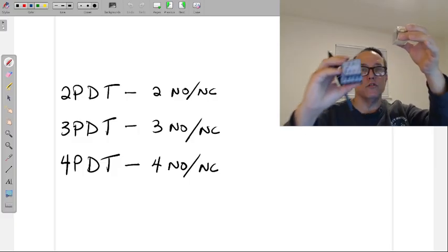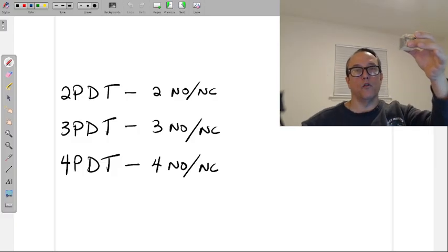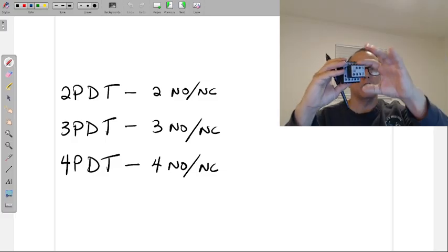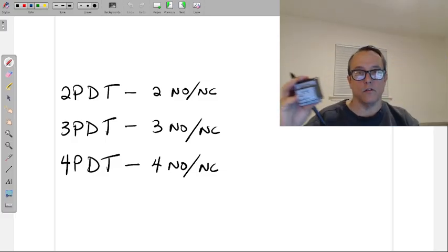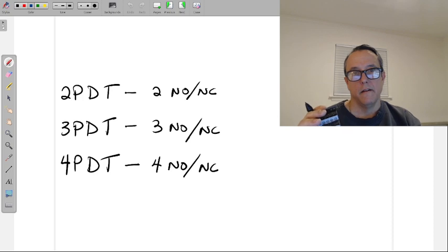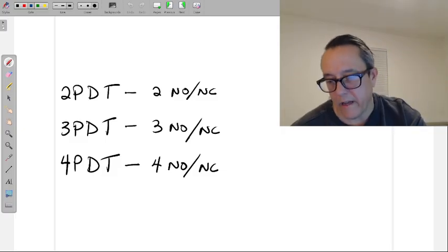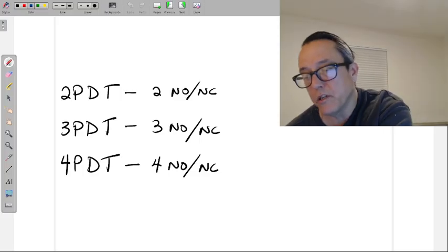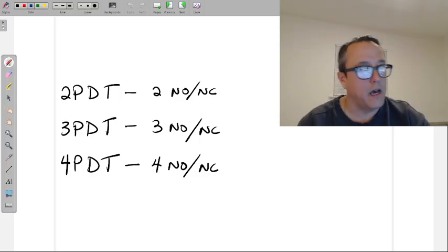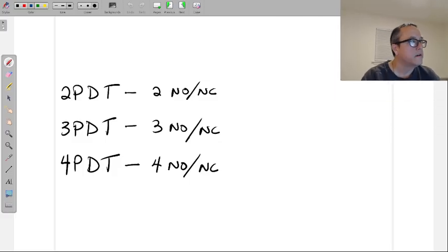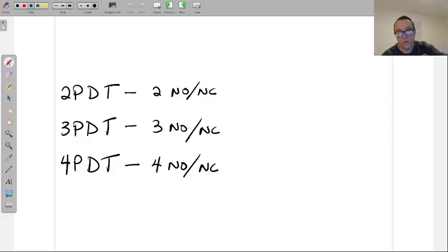I've got a bunch of motors in the control panel as well, and a bunch of auxiliary contacts for all the lights also. So that's one way to start to build a control circuit where you need a lot of uses for contacts. You throw in control relays.